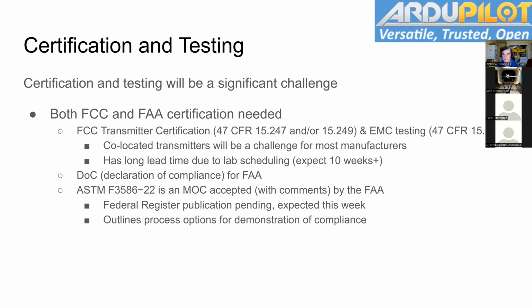There's another thing to note here in nomenclature. The FAA's definition of modular and the FCC's definition of modular are not the same. And that is a huge source of communication error in discussions here. The FCC definition of modular certification is like the little ESP32 modules that you buy that have a little RF can and an FCC ID. That's a module. To the FAA, a modular remote ID transmitter or modular remote ID device is like a little puck that's almost completely self-contained. It has a different regulatory scope under Part 89 from standard remote ID.